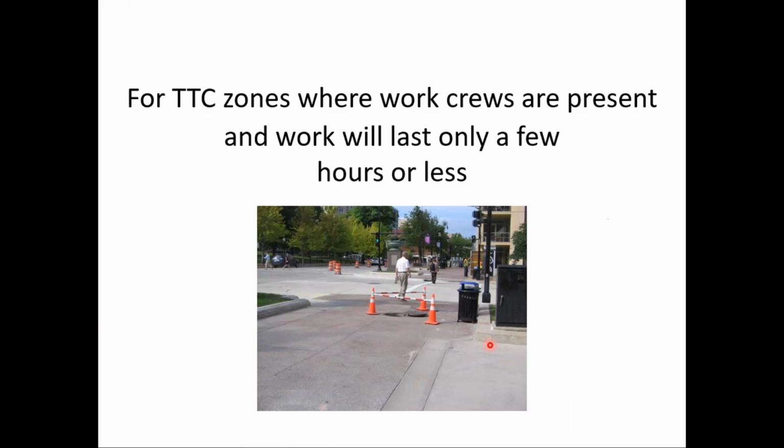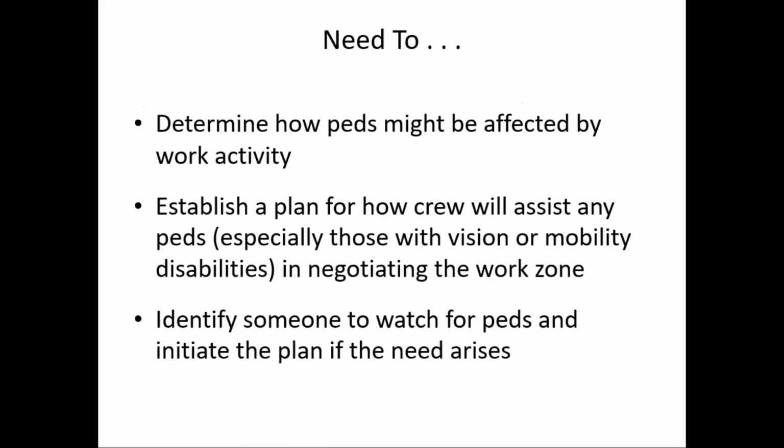In this case, for one thing, we have to warn pedestrians of this opening, the open manhole, but also we have to let pedestrians know the available route is, let's say, to the north, on the north side of this sidewalk for all pedestrians. So we have to let pedestrians know that. Establish a plan for how crew members will assist any pedestrians in negotiating that work zone. And then identify somebody to watch out for pedestrians and initiate the plan if the need arises.